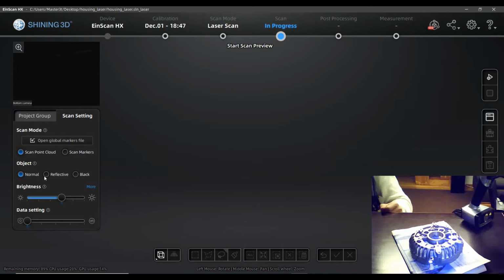You can change the mode while scanning, and you will not have any kind of problems. That means if you have composite parts that are in different condition regarding surface, for example, a plastic bumper of a car where there are chromed applications on it, or polished applications like metal polish or galvanized areas, you can continue scanning, just switching between, for example, reflective mode and black mode, where there is just black plastic.